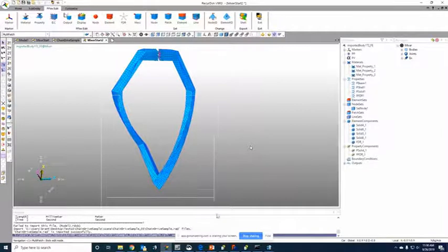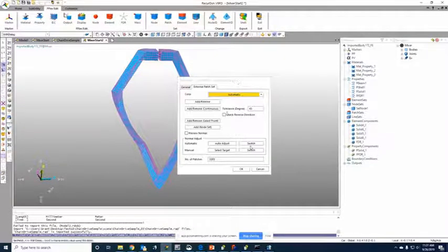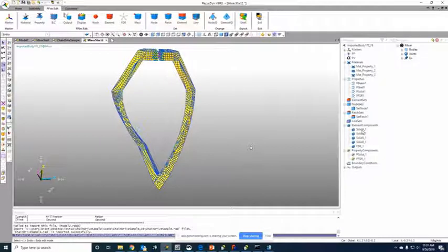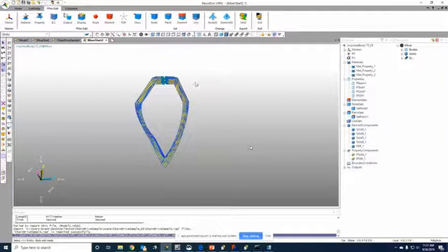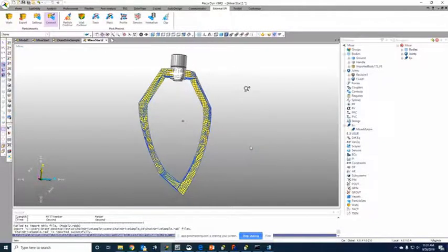You can, for example, define just part of it, and if that's the only part that comes in contact with the fluid, then you can do that. But for this example, I'm going to select the entire thing, just drag over the entire thing and say finish operation. That created this patch set over the entire body there. So that's all I need to do here. I'll press exit.